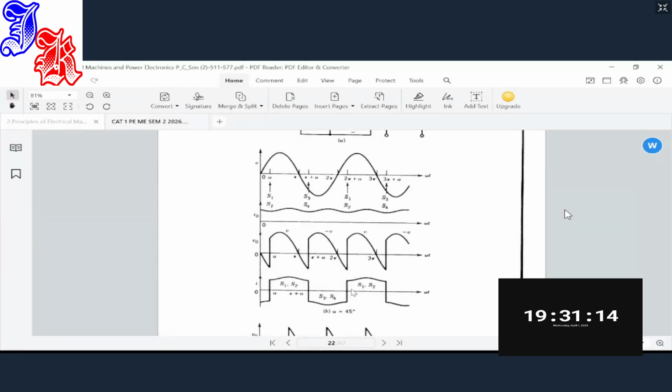Remember when you are doing your electrical machines, you're able to find it is the same machine. It can act as a motor and as a generator at the same time. If you feed electrical power to the stator and you're able to have the shaft rotating, then you can tap the mechanical energy from the shaft. The other way around, you can start by rotating the shaft using maybe wind energy, hydro energy, or whatever is turning the turbines, the shaft. And from the other end, from the stator cables, you can be able to tap electrical energy.